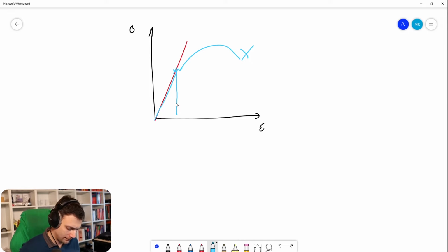So why does it get wrong, or what's the basic scenario here? Well, in FEA, you have your model consisting of elements, you know how they behave geometrically, and now you pose an external load, and you calculate the internal response until equilibrium, which means you get a displacement field, a strain field, and from the strain field you will calculate the stresses.